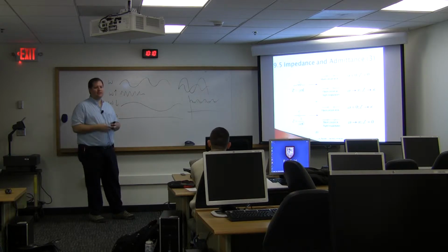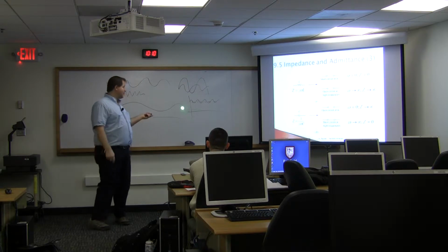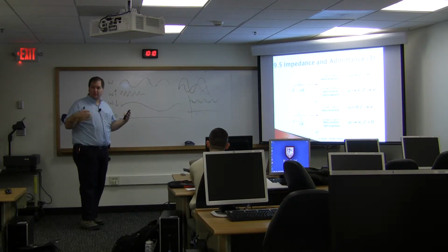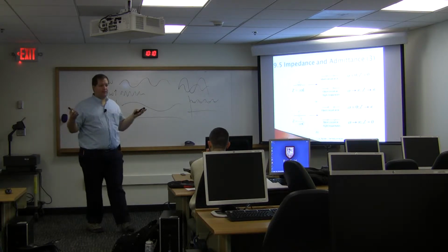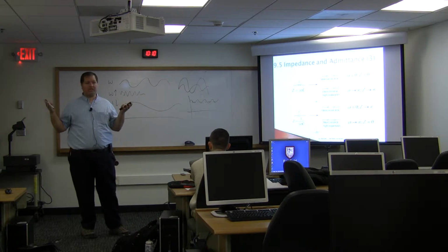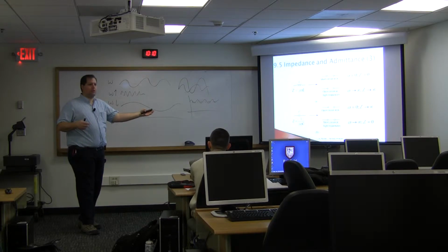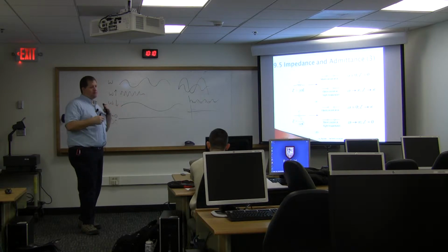Why? It inserts basically a capacitor into your circuit. And so the DC can't get through. And you can only get the high frequencies. And something has to be changing in order for it to get through a capacitor. And you can think about what is physically happening there. Well, again, with capacitors, there's only current through a capacitor when there's a derivative as a function of time. So for DC, there's nothing changing, so the derivative is 0, so there's no current. So no current can actually flow into your oscilloscope, and so it has nothing to measure. But then if something starts to change, a little bit of current gets through.